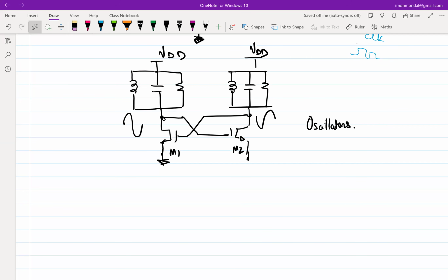Miller capacitance, it's a capacitor, right? I mean, it's one of the configurations. Okay, and you change A. So his suggestion is that you take an amplifier, connect a Miller capacitance, and you change it. Note that these have to operate at multi-gigahertz frequencies, right? So can you get a decent gain? Okay, let me address that.